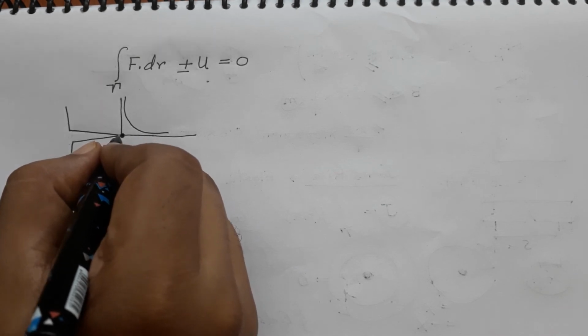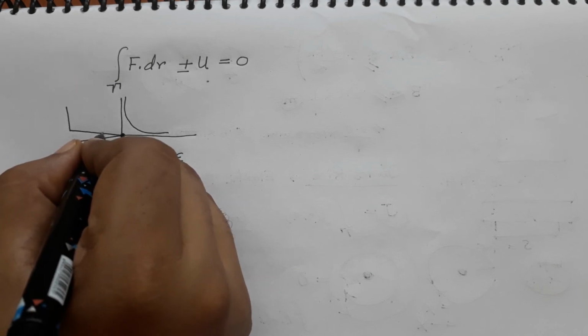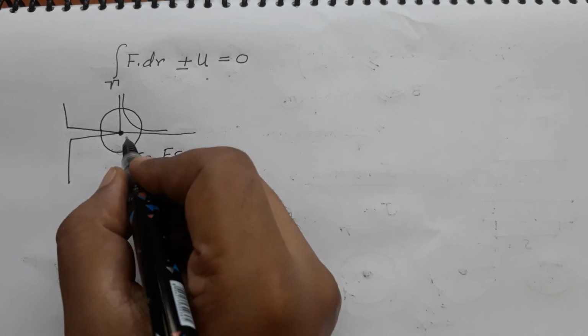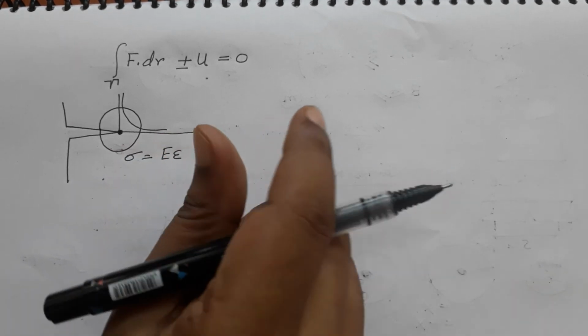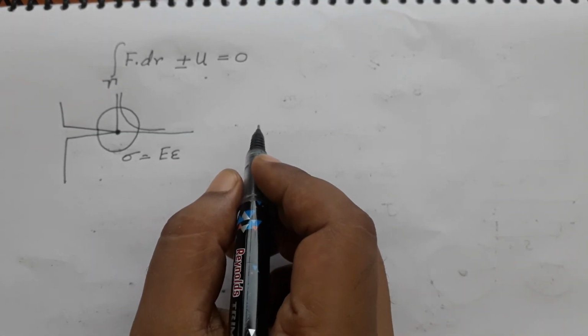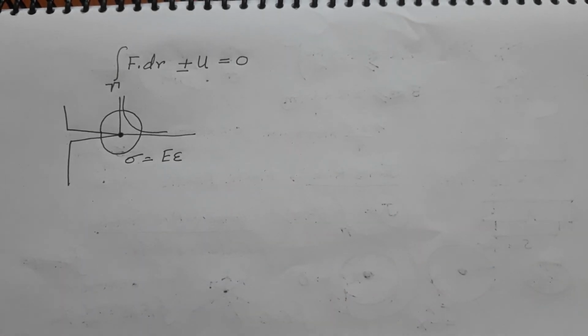Okay? And the crack tip therefore becomes a singularity, and if you take a closed path around it, that will be describing the crack, the singularity, in a very unique way. And that is how the idea of J integral comes. But why is this idea so good? Why is this idea so beneficial that it can be used, and is used in many applications?